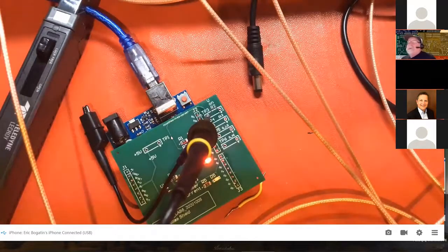Our newest one is a 1 gigahertz bandwidth differential probe, and that's where the 2 gigahertz bandwidth of the scope is really valuable. I call it part of situational awareness, being aware of the bandwidth of your signal, the bandwidth of the probe, and the bandwidth of the scope, so you have the bandwidth of the system.